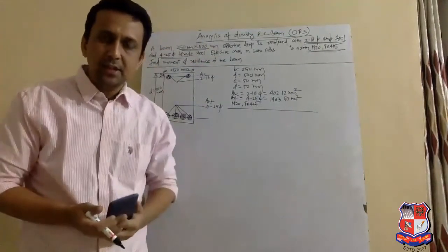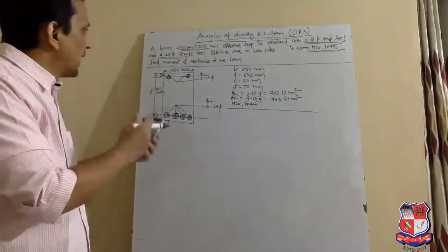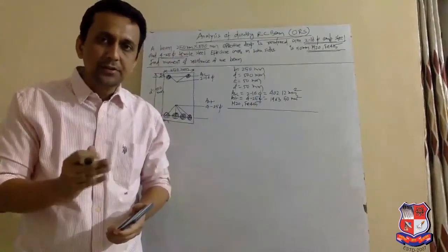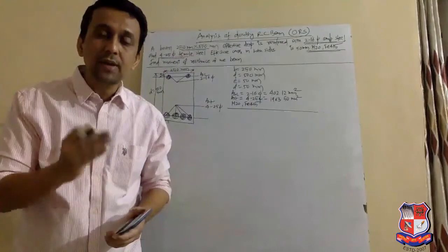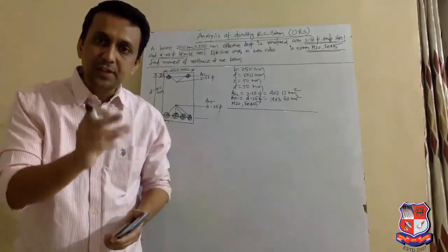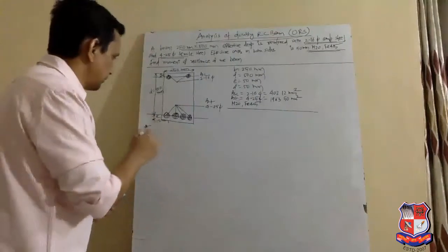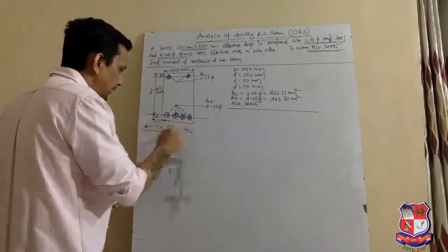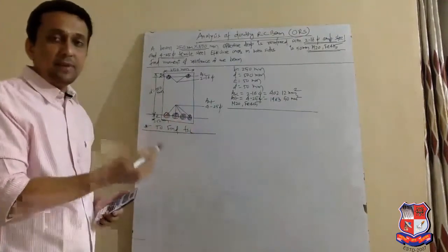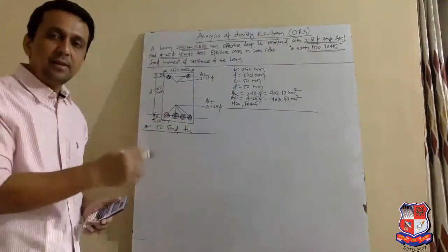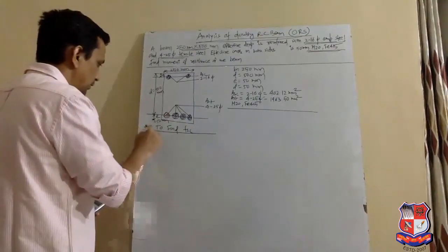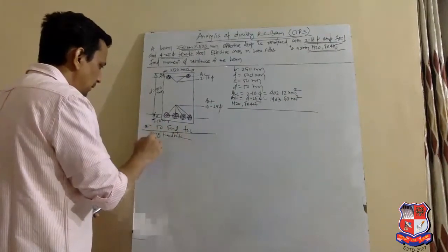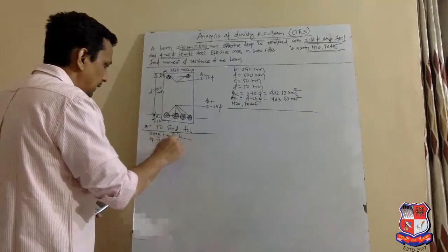In previous lecture, I have already told how to find moment of resistance of the doubly reinforced beam. First, we need to find the value of FSC, which is the stress in steel in compression zone. So first we find FSC. Here again, we will find it using handbook as well as IS 456. First, using handbook, page number 13, table F.